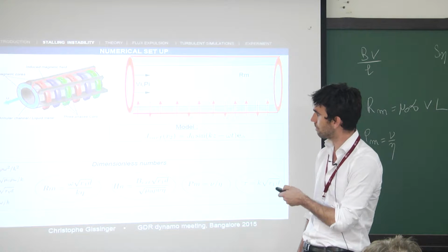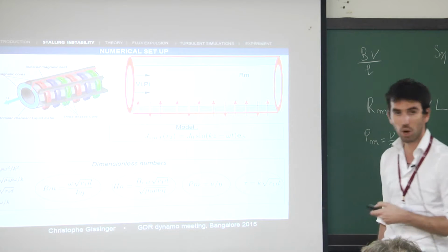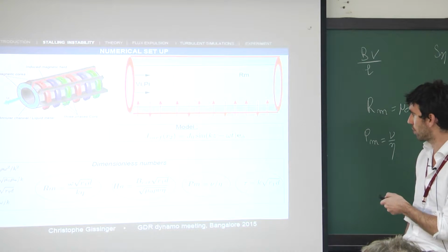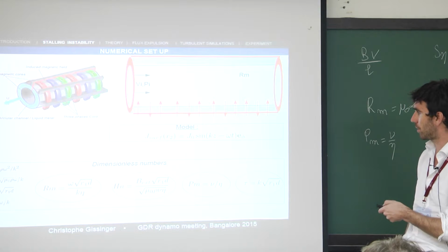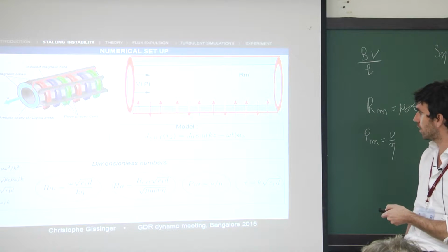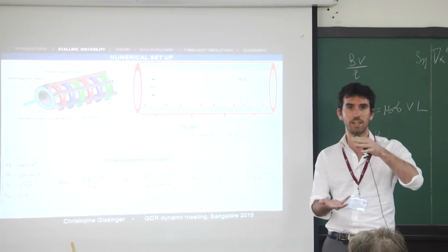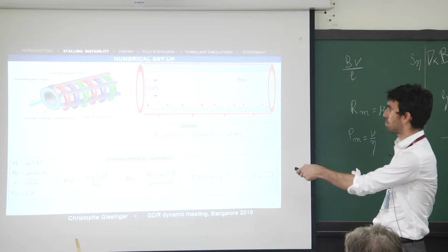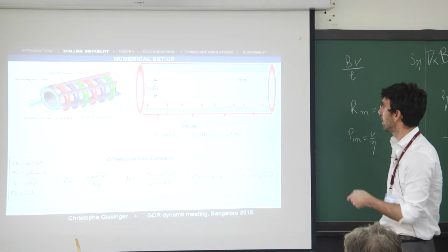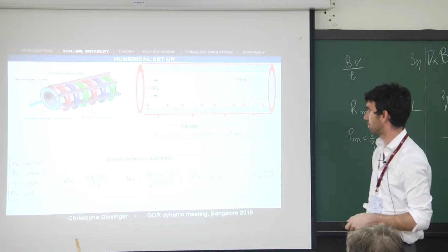To model these electrical coils, we are imposing a surface current at the external boundaries, okay? So we can choose it analytically, so we choose a very simple form. So we have a current which is like sin(kz - ωt), okay? So it's propagating in the Z direction. And the cylinder is infinite in the Z direction.